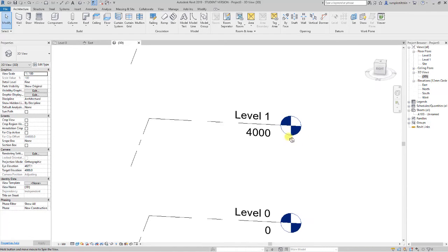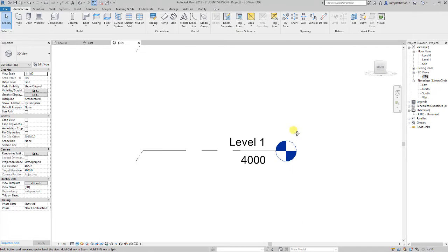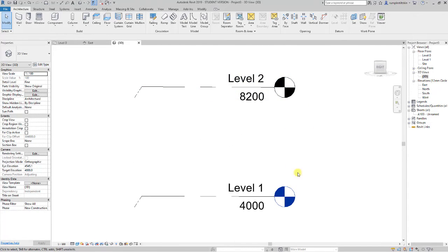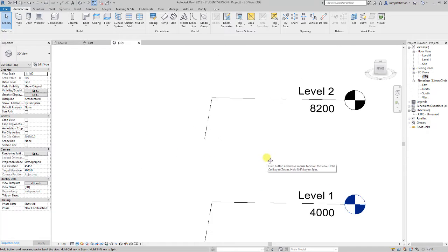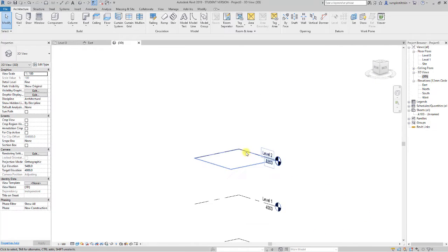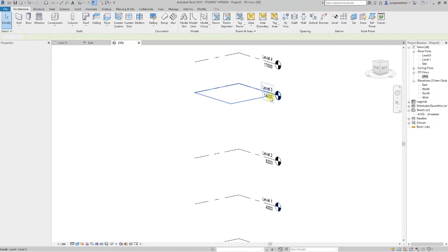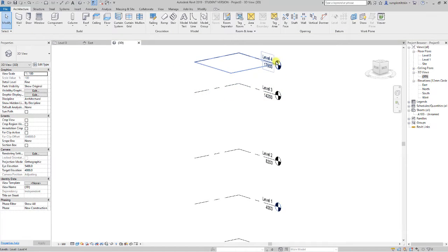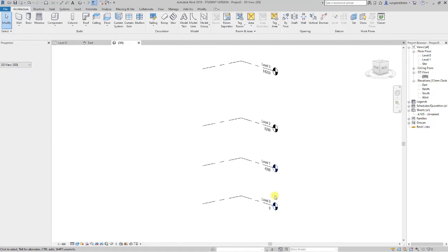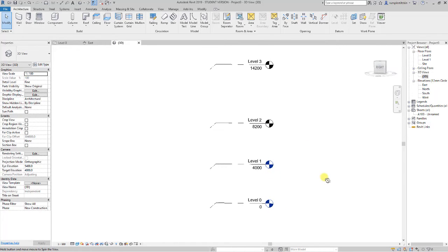And there's a significant difference between a black infill and a blue infill, in so much as if we look at the blue infills, we can see that there's floor plans associated with them. But the black infill, because we created it from just effectively copying the one inside the project at the moment, I can do the same thing, just click and hold and drag. It's really useful to create reference planes, but if you want to generate floor plans from them, then it's not actually doing it straight off the bat.